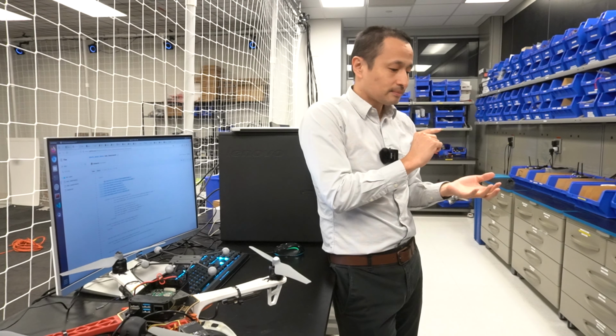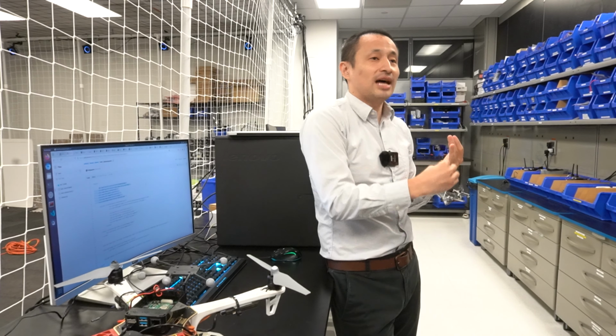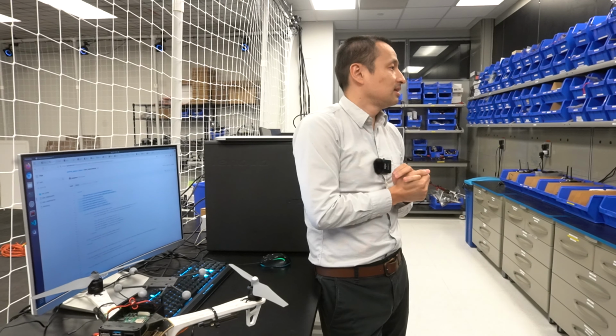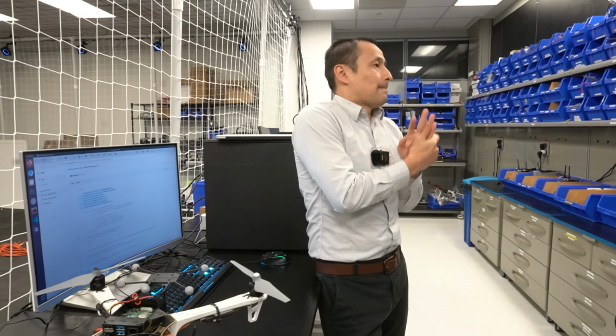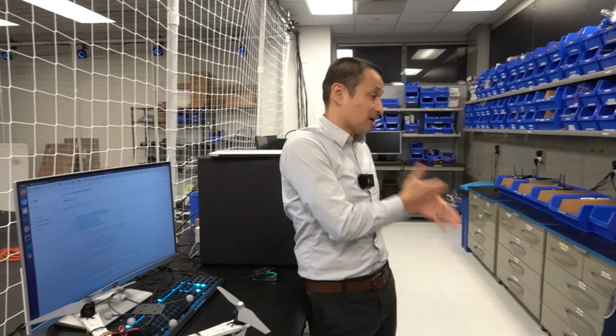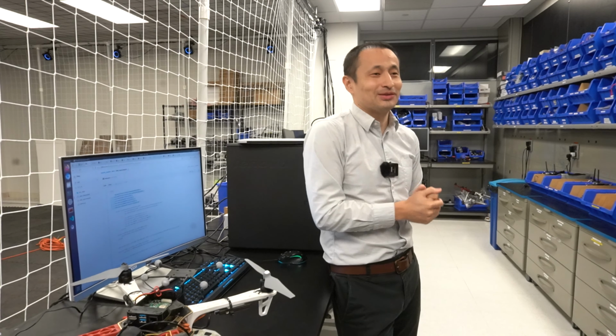And we have a carbon fiber 3D printer nowadays. We have it in the lab because we want to print lightweight and strong materials. We have plastic, yes? How is that different from a normal 3D printer? The carbon fiber is a very hard material, so if you have a normal nozzle, basically the brass, it will destroy your brass, because carbon fiber is harder than the brass. So you should have a special nozzle and special technology to incorporate the carbon fiber inside your design. Yeah, so it should be a diamond or ruby nozzle that you extrude from.